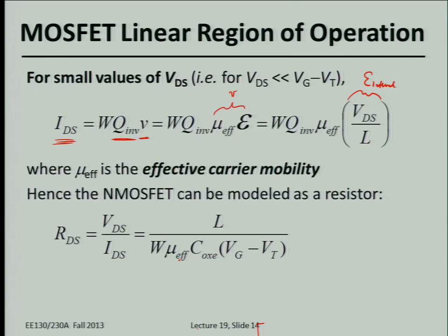So you're saying they're moving through a region of ionized? Yeah, so there are a lot of ionized dopants in the depletion region that can increase scattering, but that also exists in a doped material. You have ionized dopants all over the place too, right? But the difference is the net charge is zero for a uniformly doped semiconductor. So that's not quite the biggest reason why mobility is different in an inversion layer compared to just a doped piece of semiconductor.